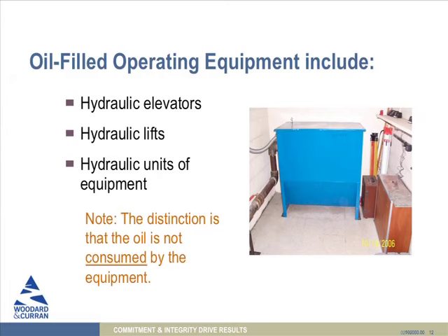Again, I just have my SPCC plan, but 2 years ago, an engineer came in, and he recommended we put a secondary containment on our reservoir. Hold that thought for a moment, because we're going to talk about secondary containment and the different kinds of secondary containment requirements. There are 2 different secondary containment rules depending on whether you're talking about the bulk storage containers, which are the typical tanks and 55-gallon drums, or something like operating equipment. So we'll go over that in just a second.